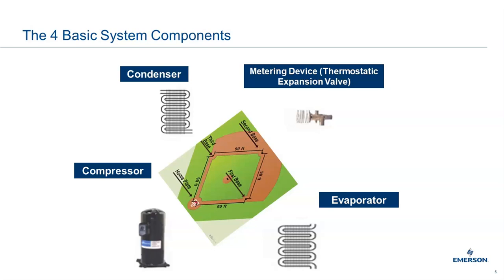Now, it rejects heat. It desuperheats, okay? And it rejects the superheat, the heat of mechanical heat, the heat from the load, the heat of compression. Whatever heat it picked up across the motor, it's rejecting that, okay? It's desuperheating. Let's go to the condenser. The condenser, it just simply condenses high pressure vapor into high pressure liquid. It desuperheats it, and it rejects the heat from the load, the heat of compression, and the superheat, okay?